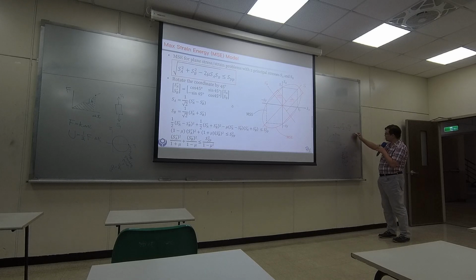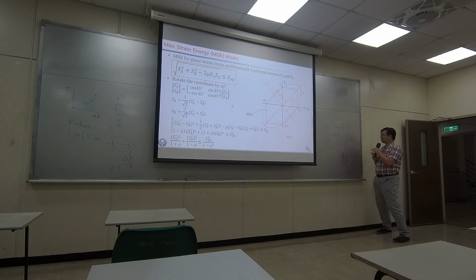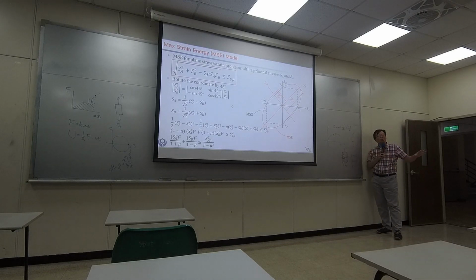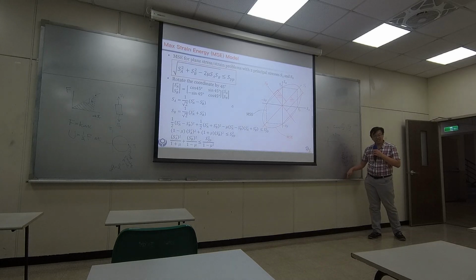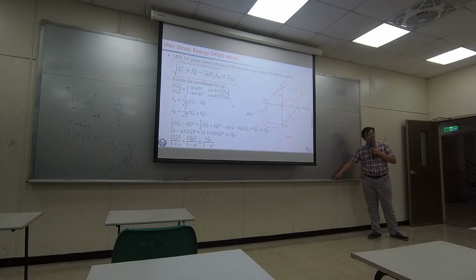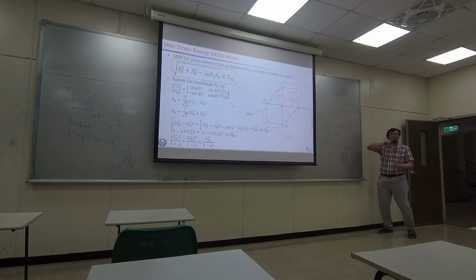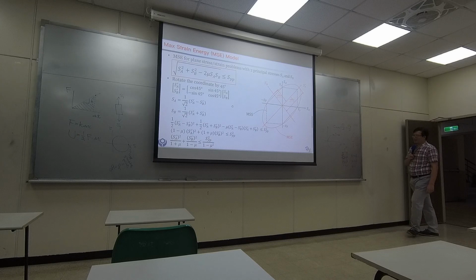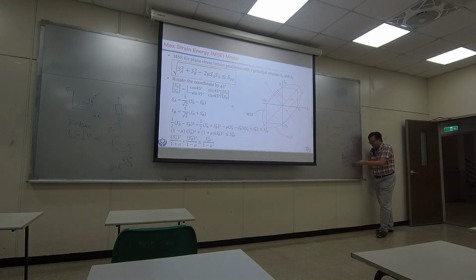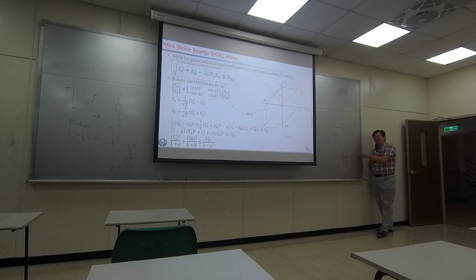If you can lengthen it and the width remains the same, that means Poisson ratio is 0. That kind of material doesn't exist. If you can do that, that means you can keep on pulling, and then you have more and more material, right? So usually Poisson ratio is a number within 0 and 0.5. 0.5 is like the theoretical extreme value for Poisson's ratio.